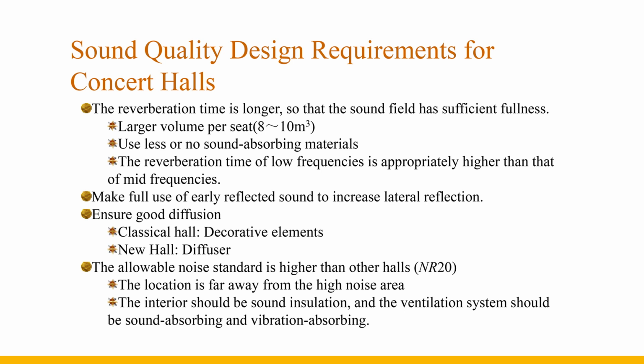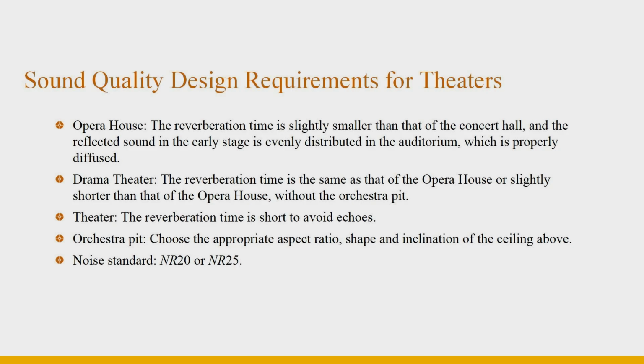The site selection should be far away from the areas with high noise. The interior should have sound insulation, and the ventilation system should be sound absorbing and vibration absorbing. In addition, a sound control room needs to be set up to meet the needs of sound reinforcement, broadcast, and recording. Theaters include opera halls, dramatic theaters, and drama theaters.